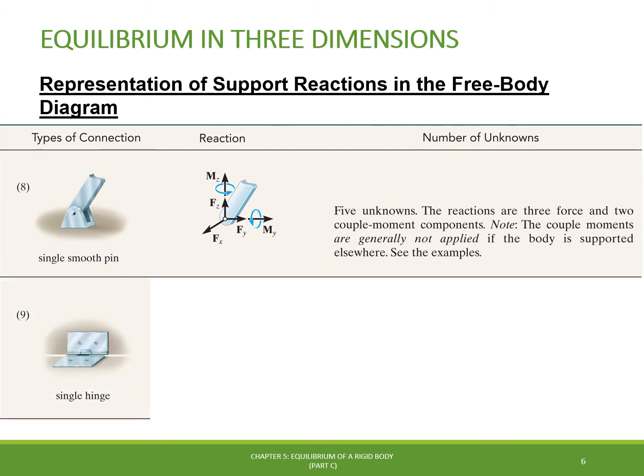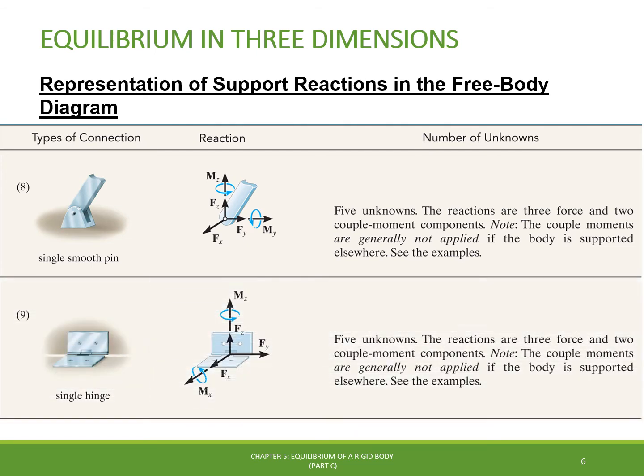Then we have the single hinge support, which also creates three reaction forces, Fx, Fy, and Fz, due to the restriction to translation, one reactive moment about the x direction, Mx, and one reactive moment about the z direction, Mz, due to the restriction to rotation about this axis.